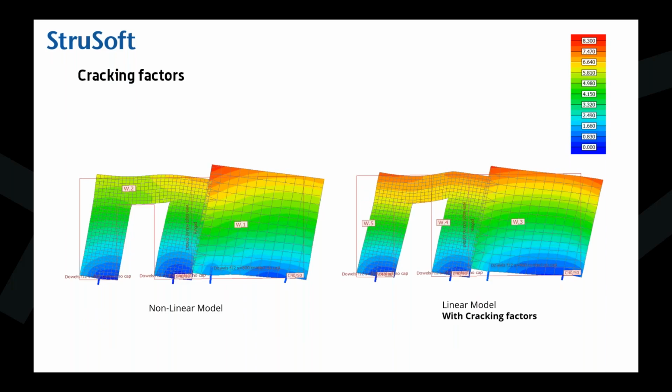But it requires a lot of expertise. And I always recommend how you do it: you do it by envelope. So first you estimate the upper bound of cracking and the lower bound of cracking, then you calculate those two states of your model, and all of your internal forces have to be inside this envelope. Because there's a lot of uncertainty, the envelope is the way to go.